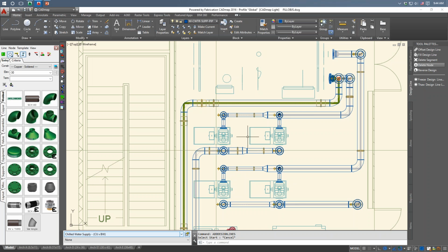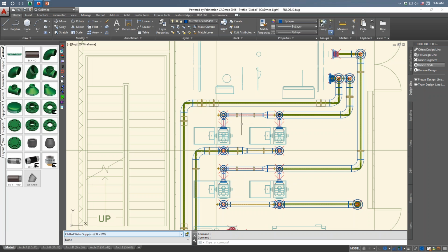All right. Well, trick for spooling. When you're dimensioning a spool and using the spool dimensions tool, that is here, it will change your snaps. We have control over what it switches your snaps to. I like mine to snap only to midpoints and nodes.